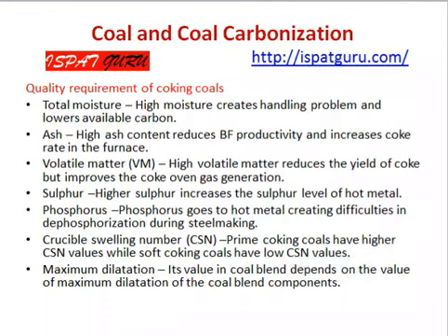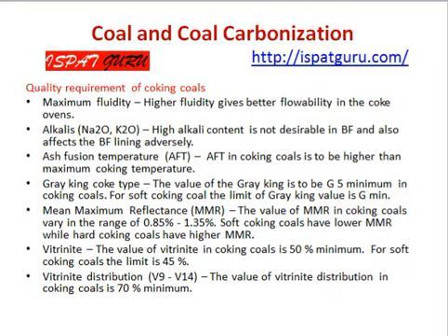Crucible swelling number, prime coking coals have high CSN values while soft coking coals have low CSN values. Maximum dilatation: its value in coal blend depends on the value of maximum dilatation in the coal blend components. Maximum fluidity: higher fluidity gives better friability in the coke domains.